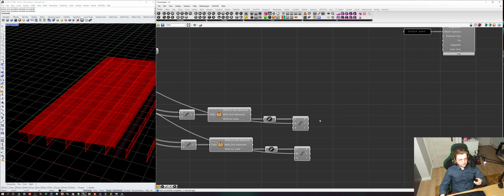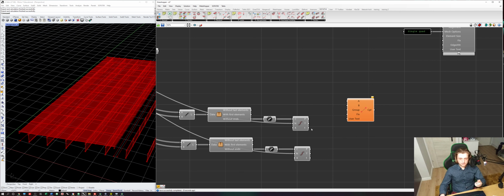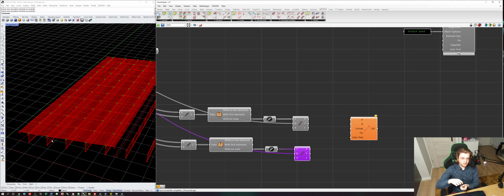Now we are ready to create the kinematic constraints. So let's go to SOFiSTiK again. Kinematic constraints, so-called couplings, are here, and I recommend to start with the top points and go to below, because points at the level of the concrete deck will appear in our model in next step. So it's natural that we want to define the displacement of the new points as a displacement of the points that already exist.